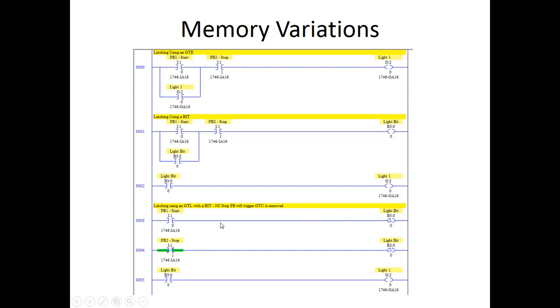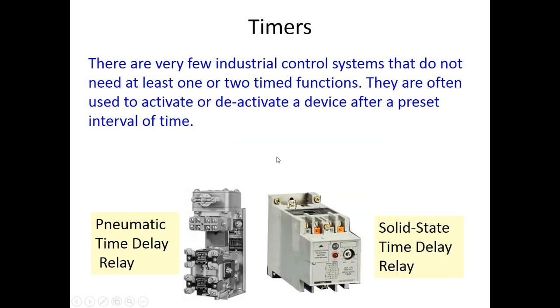The difference here is between rung 3 and rung 4, which would be your latching and your unlatching. You could have 20 ladder logic rungs here. So it might be difficult to see if this was latched and if it was unlatched, if these two items were separated by quite a bit of additional programming in your program. Here it's all right there. So it's up to you. Some people use latch, some people use unlatch, and it just depends on the way the program looks.